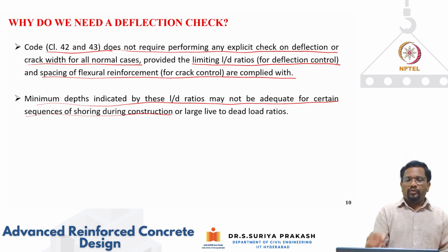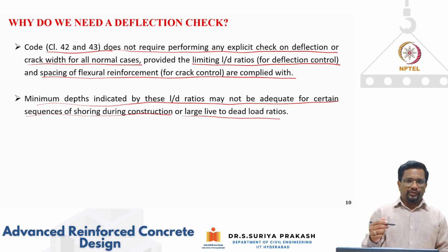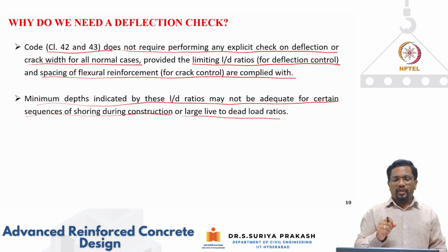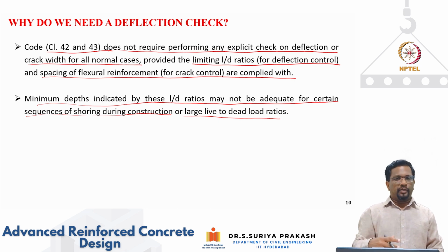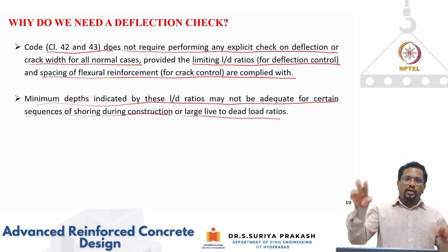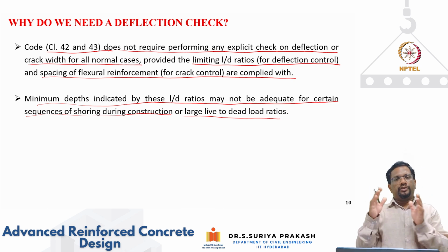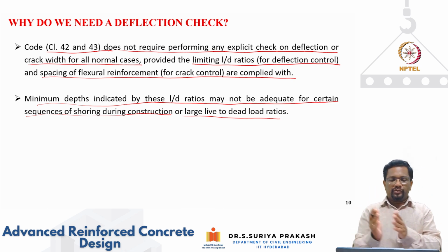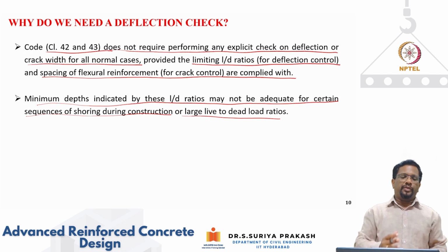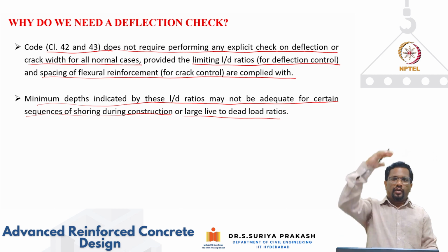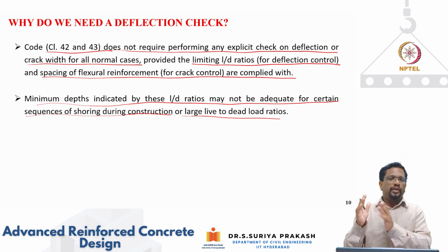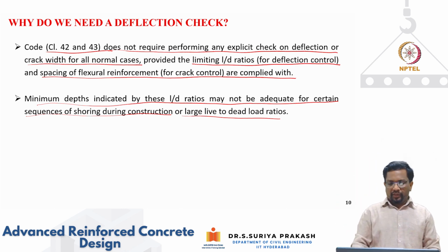Also, another important aspect is when you have a large live to dead load ratio, in that case pattern loading will come into the picture. Then your L/D ratios, whatever is given by the code, may not be applicable. So if you are using those L/D ratios, then your live load to dead load ratio also should be within a limit. And we also need to make sure that the structural system is shored, or supported during construction, for a stipulated period of time.